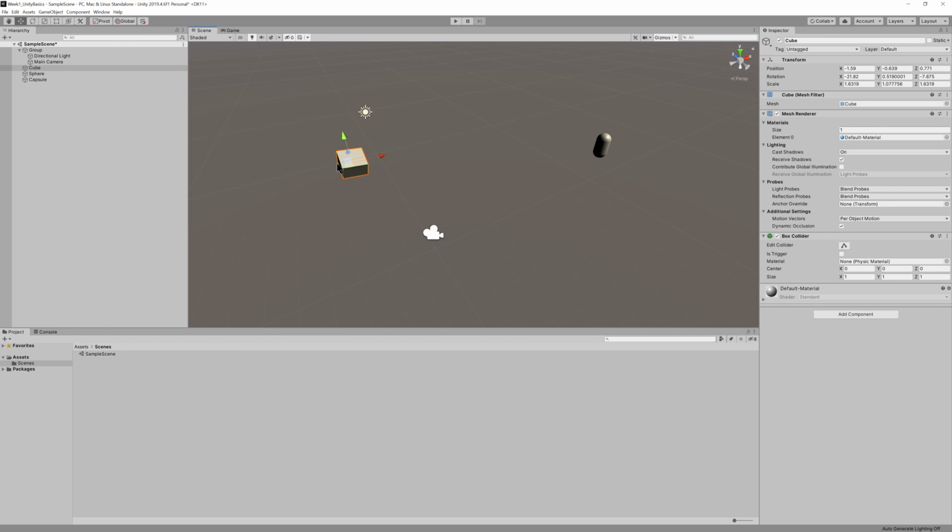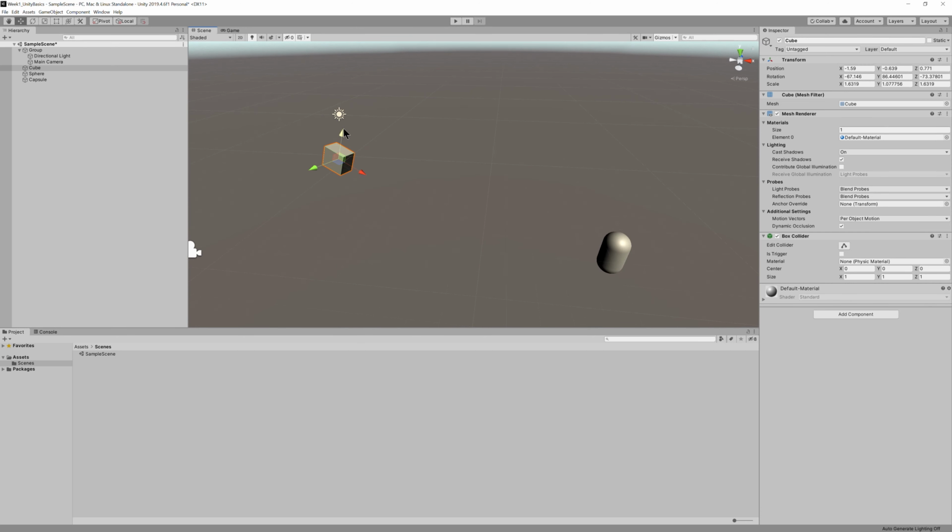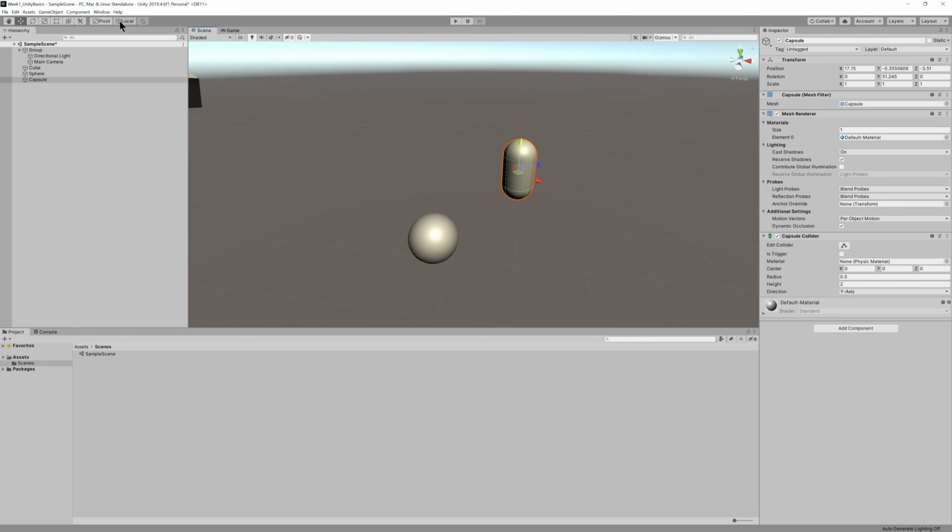If you select one of your objects, hit the E key for rotate, and rotate your object, and then choose local instead of global. Now move to the W key for movement. What you'll notice is that the forward Z vector, blue, no longer is in the same direction as the world space vector. In many cases, it's far easier to manipulate an object from its local coordinate space than it is the world space. Now, just like local and global, there's also pivot or center.